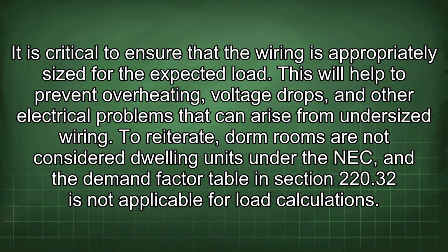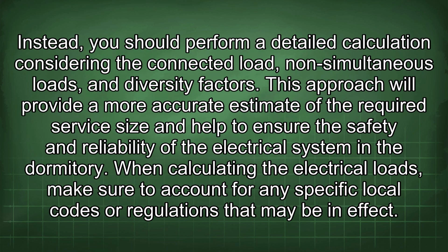To reiterate, dorm rooms are not considered dwelling units under the NEC, and the demand factor table in section 220.32 is not applicable for load calculations. Instead, you should perform a detailed calculation considering the connected load, non-simultaneous loads, and diversity factors. This approach will provide a more accurate estimate of the required service size and help to ensure the safety and reliability of the electrical system in a dormitory.